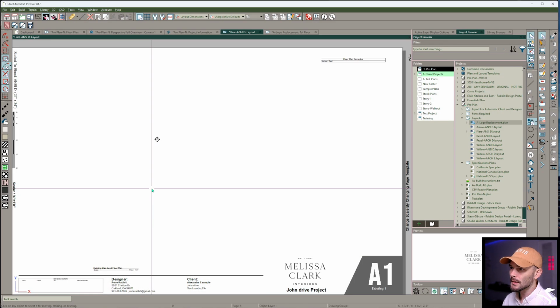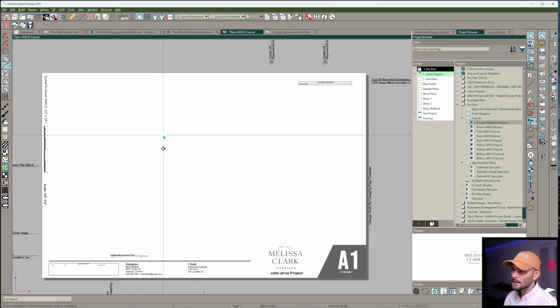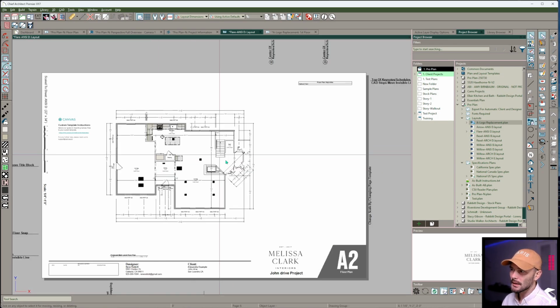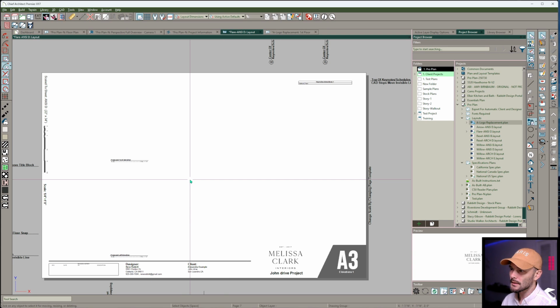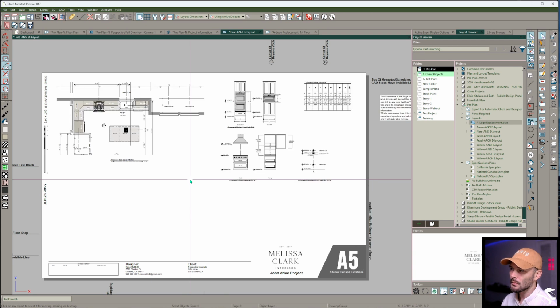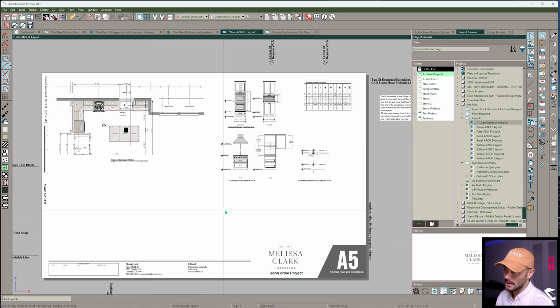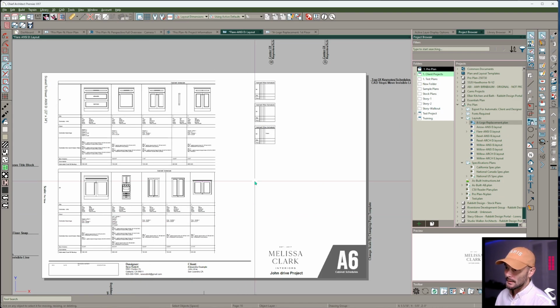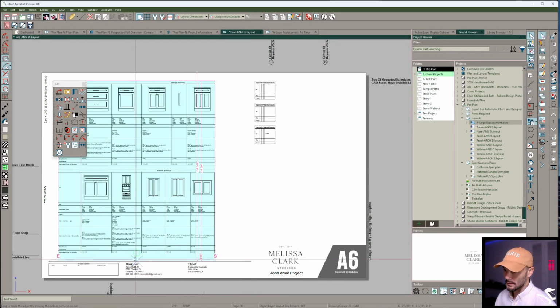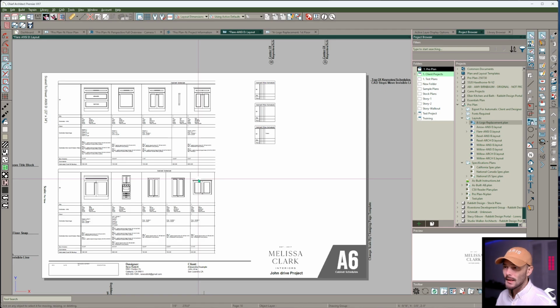All right, that building's on the plot plan. That's good. This is an existing sheet. Maybe they delete it, maybe they don't. Here we go. That's being sent to view already. And then we could, of course, populate some of these other views. And this is looking pretty good. If I wanted to be really nice, I could send the elevations already to this plan, but I'm not going to do that this time around. And it looks like they might have to conform some things in terms of the window schedule. And so this is it. This concludes it. We've transferred this plan over.